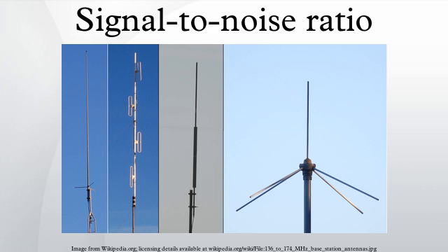Difference from conventional power: in physics, the average power of an AC signal is defined as the average value of voltage times current. For resistive circuits, where voltage and current are in phase, this is equivalent to the product of the RMS voltage and current.